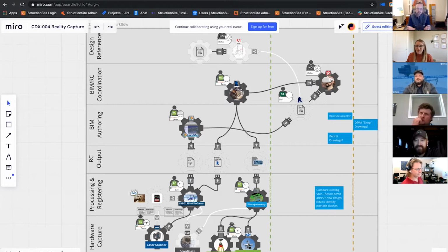I think we've always had to debate internally, do we really want to make this wall not plumb? Because it's going to look like garbage inside the design software. Revit doesn't like non-plumb things at all, period. It hates them, unless you use 2021, where you can actually provide a cant to the wall that wasn't there before, but it just doesn't look good. So do you need it that way? Do you need to have that non-plumb?